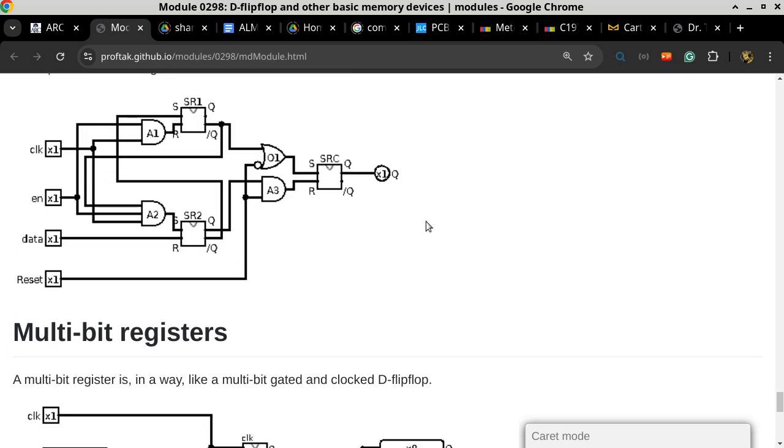So the last detail here is we have one additional input pin called reset. This is the reset pin. The reason it is important to have a reset pin is because when you start up a computer, there's no known state. That means the SR latches, especially the last one, are going to have some state, but the state that it is in is really just kind of random. Do you want the components of your computer to start up completely in a random way? Probably not, right? So you want it to start at a particular state.